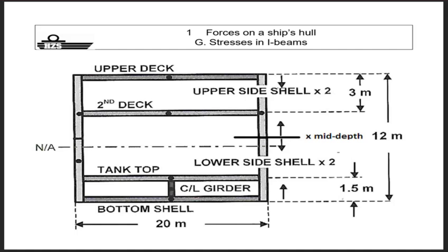Are you able to calculate now the stress levels in the upper deck, the stress levels in the second deck, the stress levels in the tank top and bottom shell? Yes, you're capable of doing so. What do you need to know? Of course, the bending moments. The bending moments are the calculations we did the past weeks. Suppose you have your bending moment given, and I will give you a bending moment as an assumption. What will be the evolution of your stress at a certain point? Suppose we are at a position where your bending moment is max. It's always nice to look at where your moments are the max, because it gives you the maximum stresses.